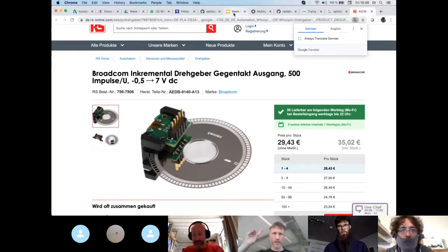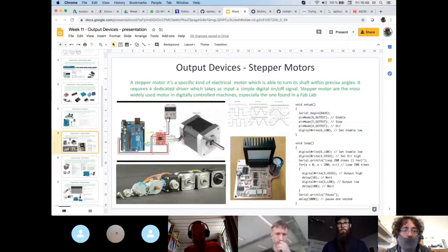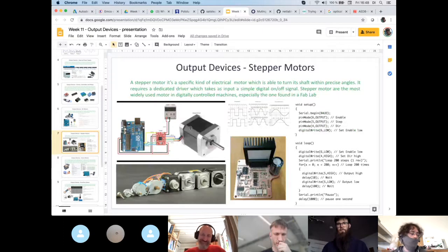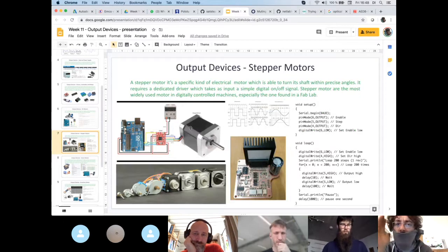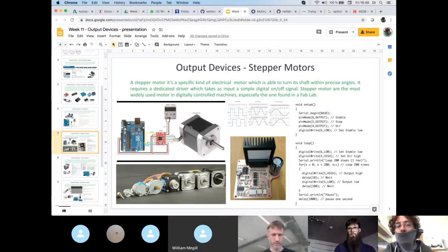Extra credit from Neil. One thing that is worth mentioning, guys, the most advanced stepper drivers can also measure the status of the motor according to the current. As I told you, for your DPV harness, I think in one of the last meetings, they can detect if the motor has lost steps, for example, but they are not as precise as the encoder, of course.